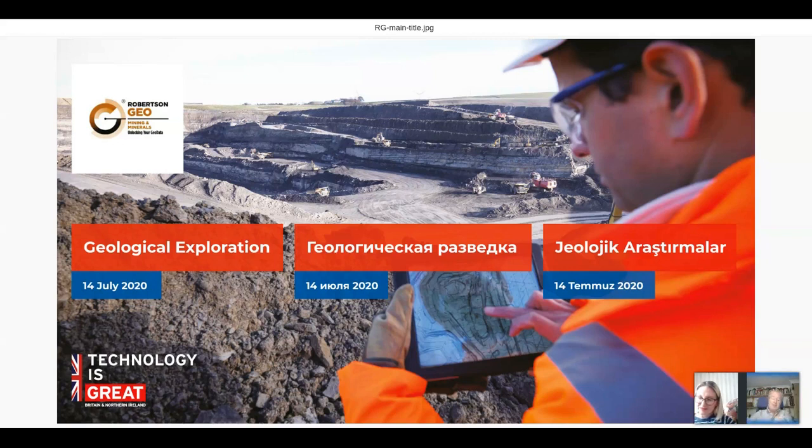At the top end, first of all, the depth limitation on the majority of tools is around 2,000 meters. There are some special circumstances for particular tools a little less than that. The camera that I mentioned we've developed is capable to 3,000 meters, and we will be producing next year. I mentioned we're releasing some new product, so that will have capability to 125 degrees downhole conditions, and up to 3,000 meters depth.